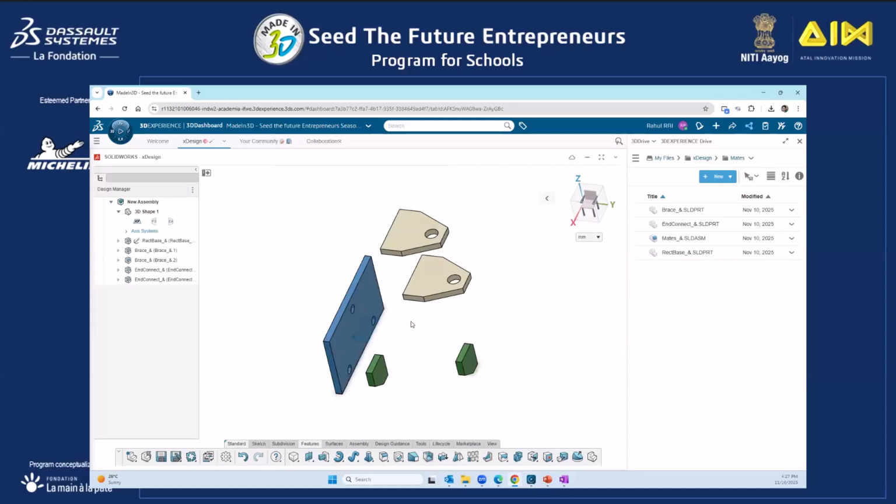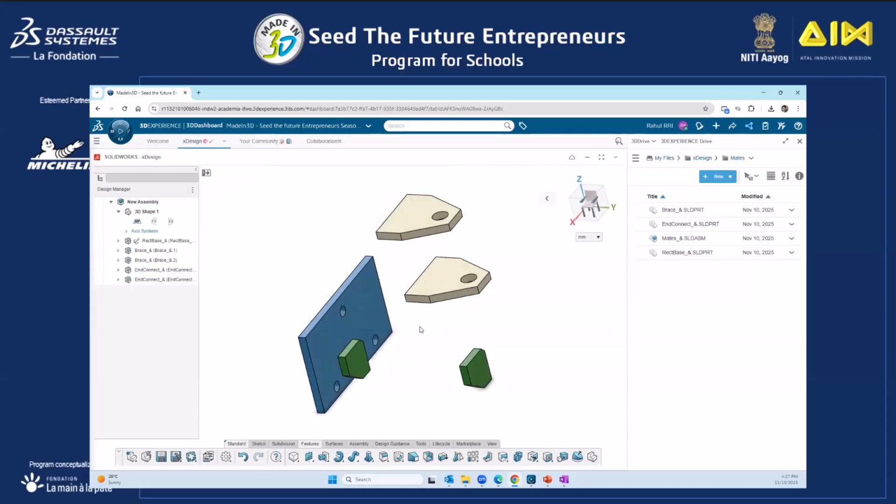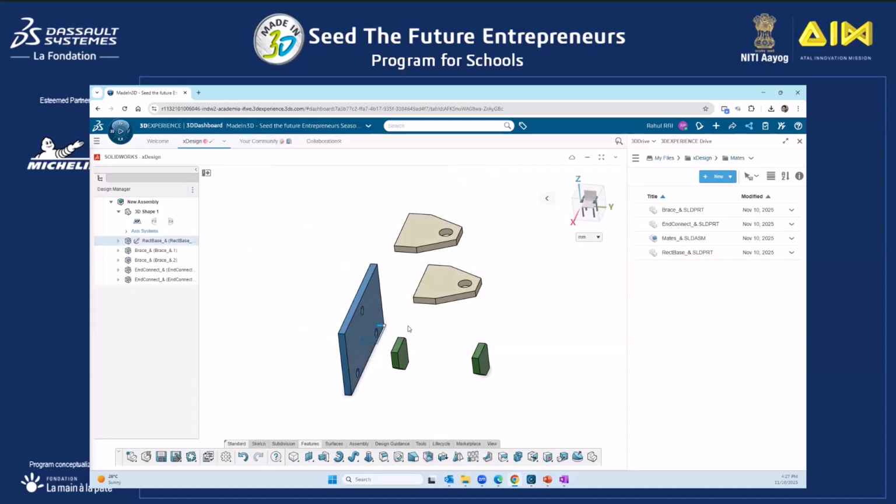Similarly, in XDesign also, we have these tools like glue and stapler pin and other things. We call them mates. Mates, you can find them in the assembly tab, and there we have this option called mates. When you click on it, a dialog box will appear.